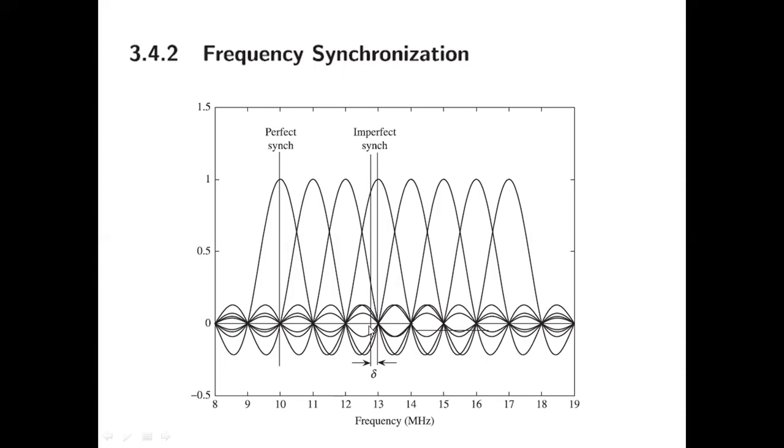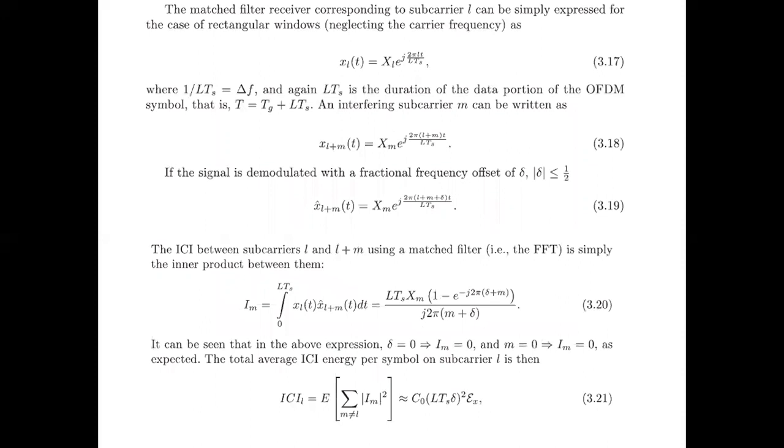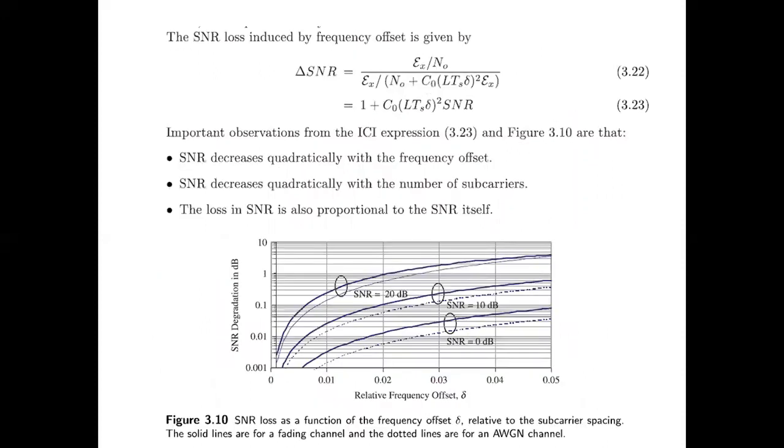Now, when does that happen, by the way? That happens whenever there is a change in the carrier frequency at the receiver or the data itself. This happens due to Doppler or the frequency offset. Say you are traveling in a car at a carrier frequency of 900 megahertz. What's going to happen? Say it becomes 900.01 megahertz because your vehicle is moving towards or away from the tower.